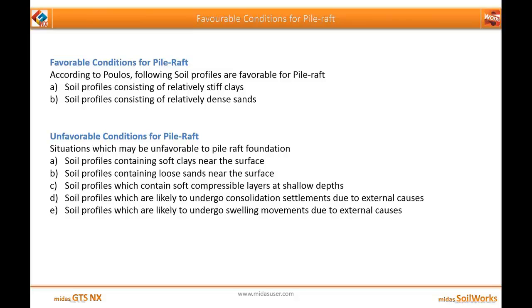Similarly, wherever there is a chance of consolidation, like where there are soft compressible layers at shallow depths, or where there is consolidation settlement due to external causes, what happens is that the raft no longer remains in contact with the soil, and all the force is then taken by the piles, leading to excessive settlement in the long-term cases. And finally, we have soil profiles which are likely to undergo swelling movements due to external causes, and it causes tension in the piles. So these are basically the favorable and unfavorable conditions for pile raft.